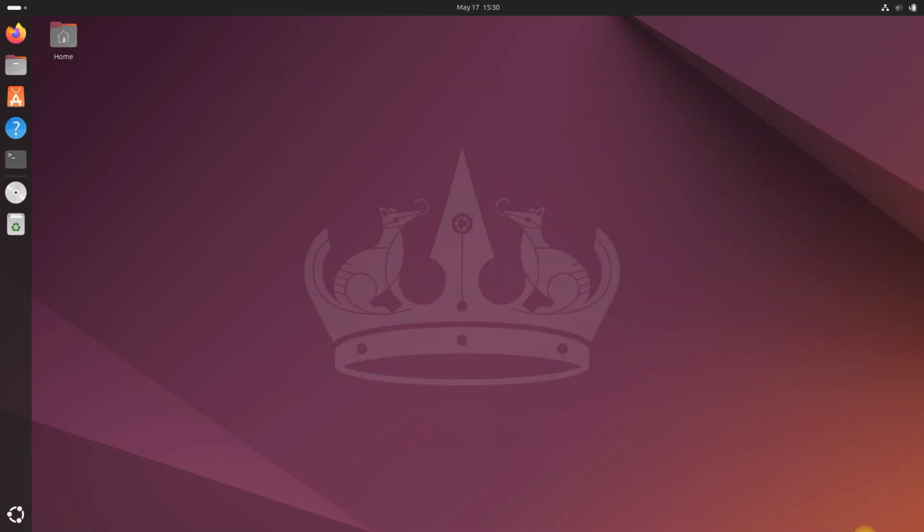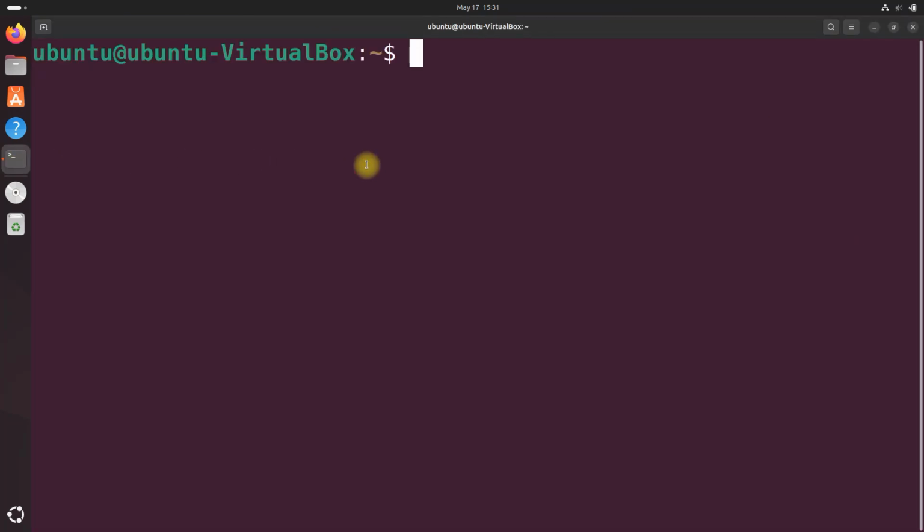Now I'm going to show you how to create a YAML file, or just a text file, which will contain our desired parameters. We will then import that YAML file into a launch file and launch the robot in Gazebo. So let's do that now. This is actually more flexible than doing all the hard coding that we did in our program, because we've got defaults that are set